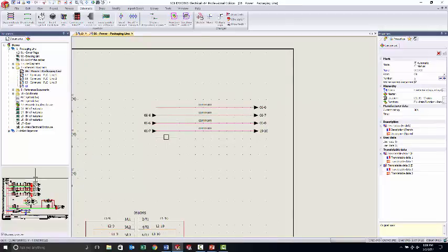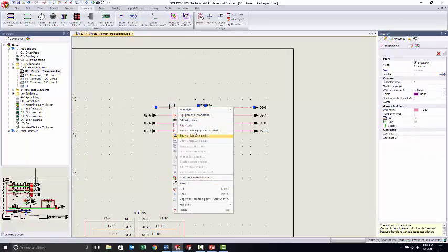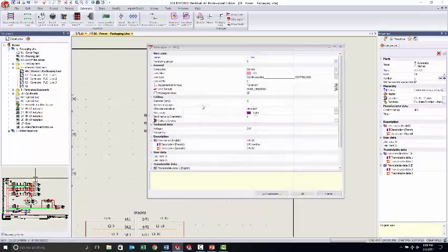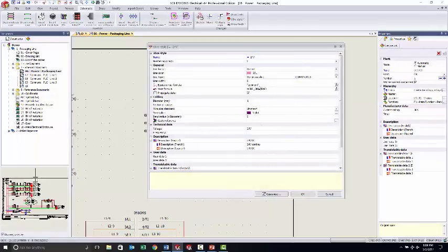For that trick to work, you need a method of having, in the case of a ground, you would have gone through and made sure on every sheet that you're drawing ground wires, you manually marked them all as ground, or your wire style has an equation that always equals ground. Yes, that's what I would do. I've got a lot of people that actually use a common for their grounds. They either use GND, which is the one that I see the most. And so when they are looking at that wire style, their formula just says this. And then, yes, all of those would be automatically connected up.